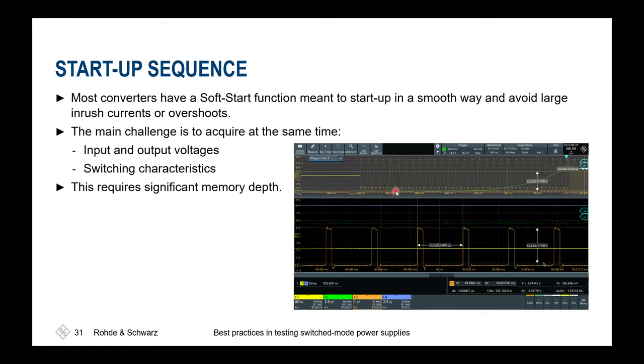So it might not take only 8 cycles, it takes maybe 8.5 or 9 cycles to get the reference voltage out of a certain switch power supply. And then you could start debugging in your design how to power up these different supplies and still ensure that you're not exceeding the maximum power consumption at the input port of the device, and also ensure that a sufficient amount of power is always provided to the different parts of your design.